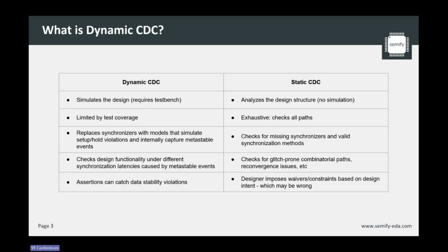Something kind of important to note is that static CDC does leave some holes purely because there's always going to be some sort of designer imposed constraints. And anywhere where there's some sort of human intervention, there's possibility for error to arise. Dynamic CDC kind of aims to bridge this divide because once you have a good model, it will always inject metastability into any synchronizer that you instantiate.